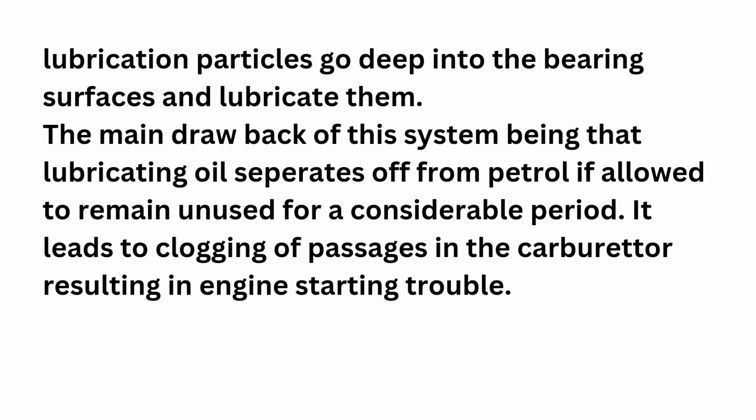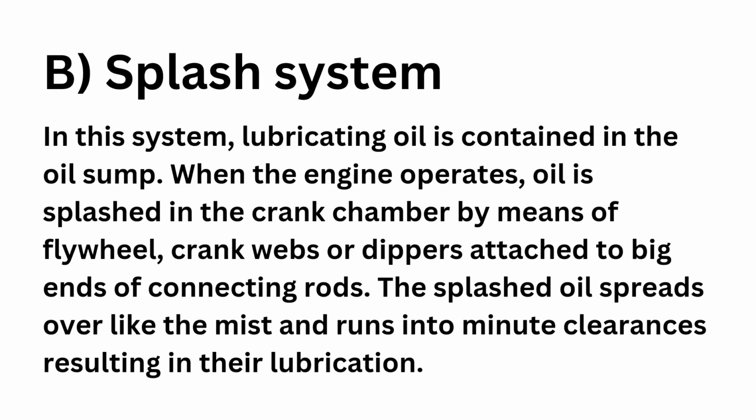The main drawback of this system being that lubricating oil separates off from petrol. If allowed to remain unused for a considerable period, it leads to clogging of passages in the carburetor, resulting in engine starting trouble.